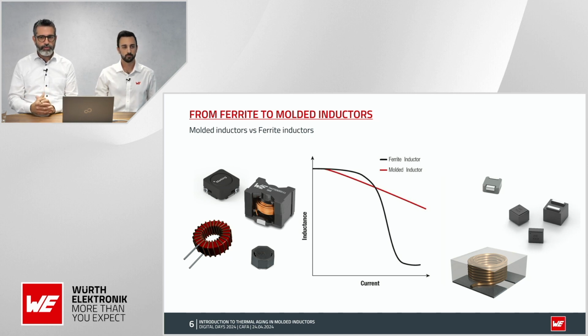And then you will lose the inductance, so you cannot store much more energy in this construction. Therefore they need air gaps in their construction to increase the saturation current. But this will reduce the permeability a little, and then you will also reduce the inductance, so in the end you need to add a few more turns.